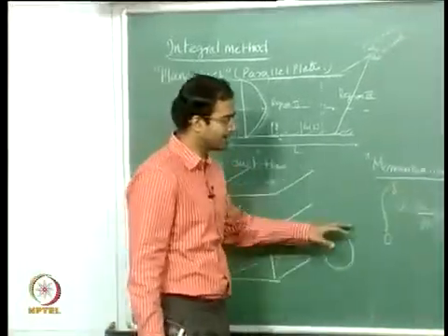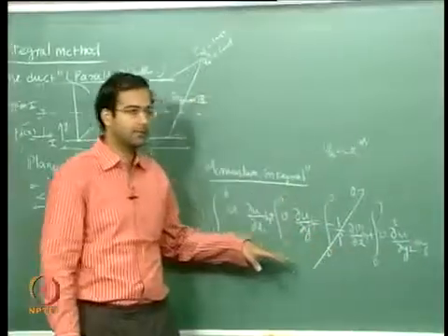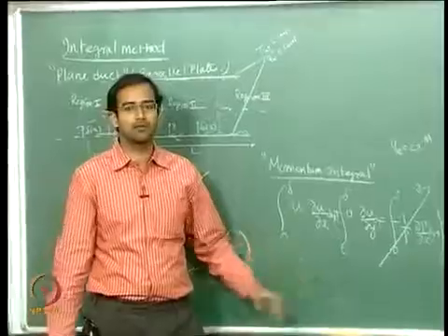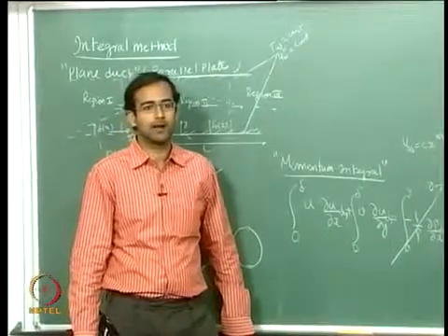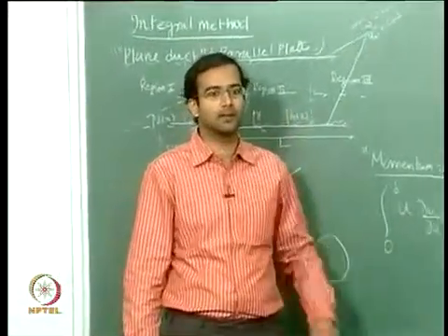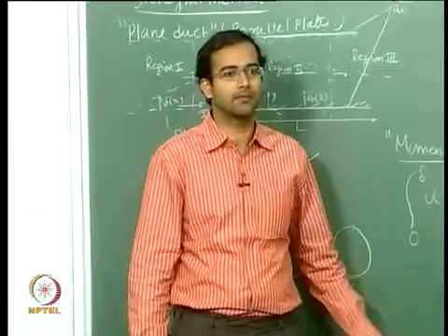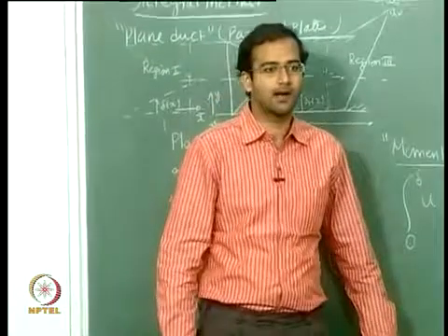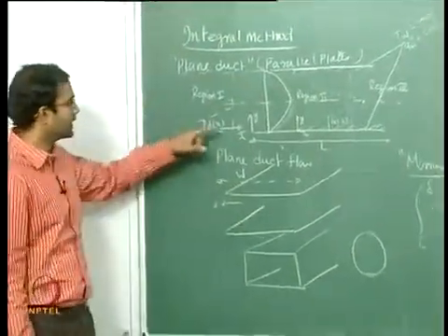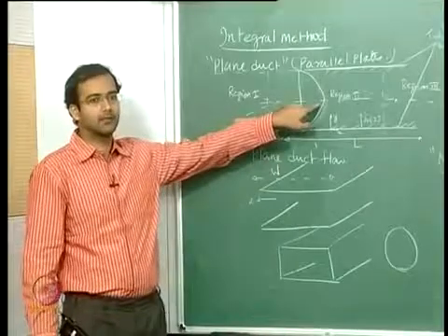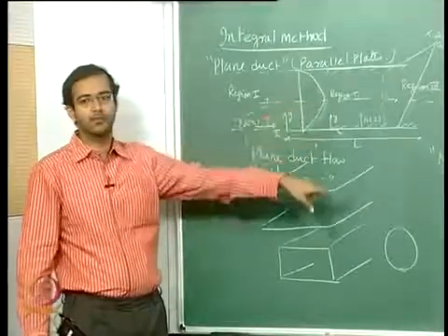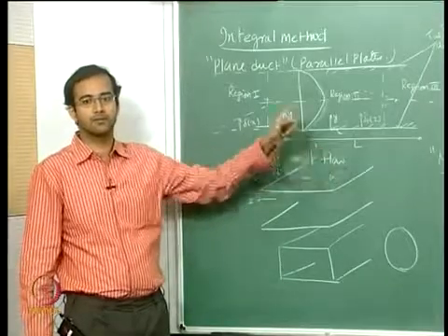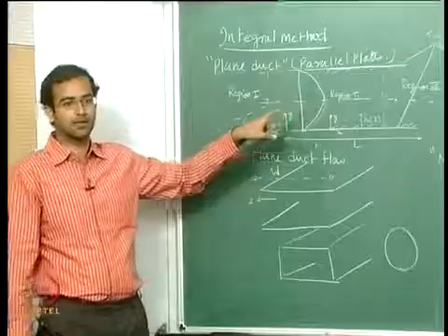So if you look at the initial part of the boundary layer development, you can make an approximation that this is 0 and this is like now a flat plate flow past a flat plate. The same way that you did the momentum integral there, the same thing can be applied, but this will be a very big crude approximation, and you cannot get an asymptotic solution for the fully developed case from this, because the momentum integral is not valid for the fully developed case. So that you should keep in mind.